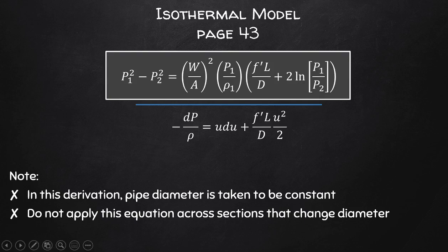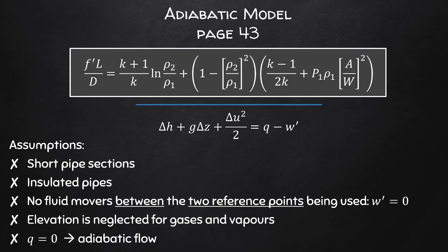we have one diameter that we can actually do the sort of calculation. If we have a different diameter, the following derivation will not apply. We will see later how sudden changes in diameters affect compressible flows, and so you'll understand why we don't tend to include reducers and enlargers. That being said, if you come across a change in diameter and you're doing a mechanical energy balance, you can simply just split your analysis at this junction where the diameter changes so that you have more terminal points, and the calculation then becomes more trivial in that regard.